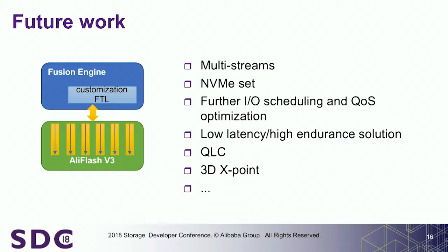So we are also looking into the opportunity to combine multi-streams, NVMe sets, further I/O scheduling and quality of service optimization, low latency, high endurance solutions, QLC. I think the industry right now is moving to QLC, so we're also working on it. Also 3D XPoint. So all those innovations into our Open Channel platform.